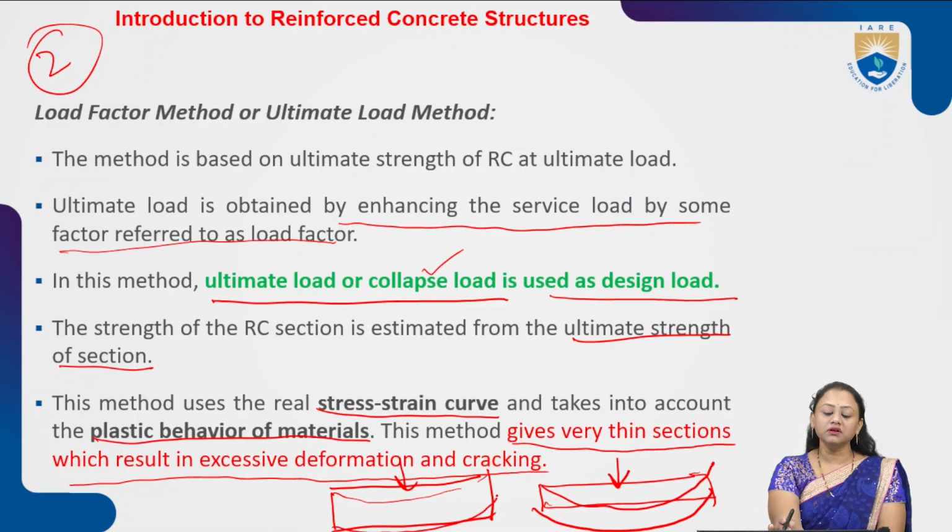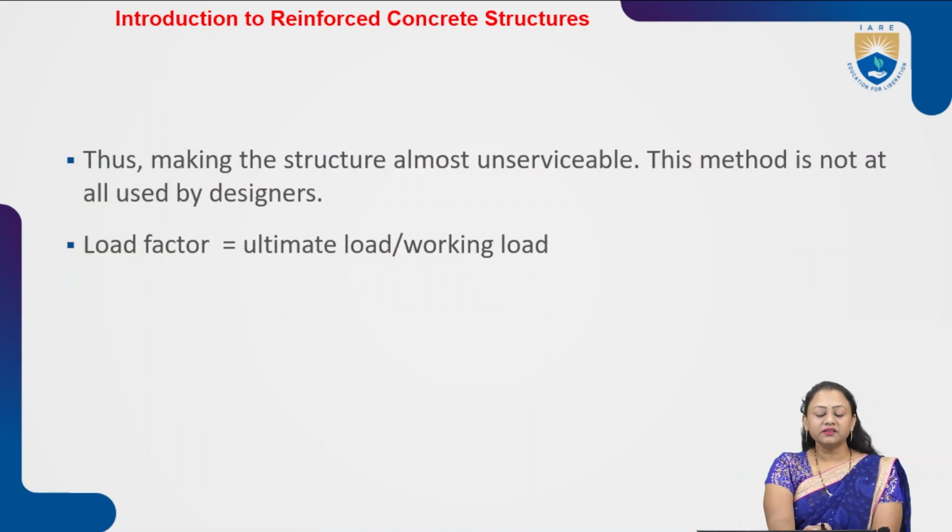So in this method, we are going to get very thin sections which result in excessive deformation. These are the points to be remembered in the load factor method or ultimate load method, thus making the structure almost unserviceable. So due to the load factor method, the structure is almost unserviceable and this method is not used by designers.